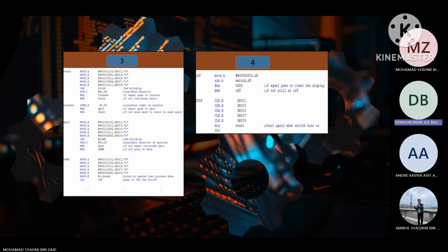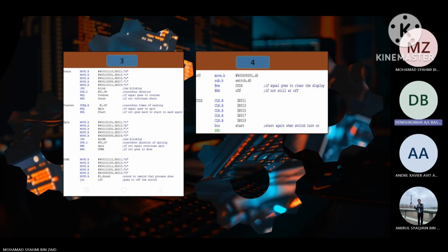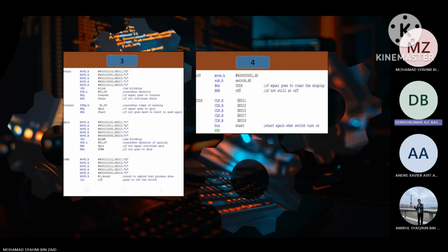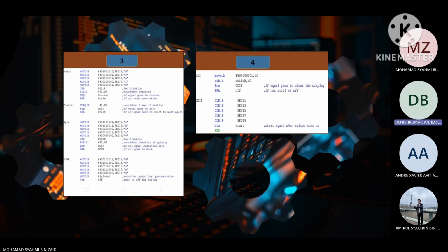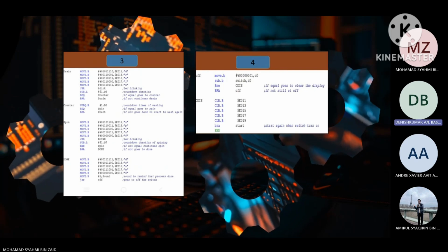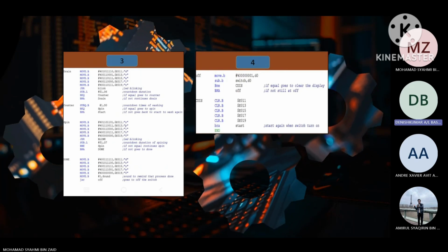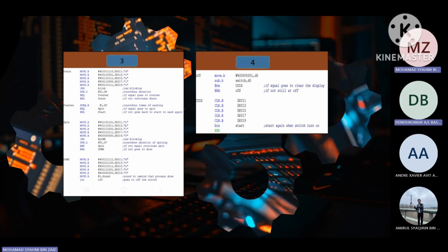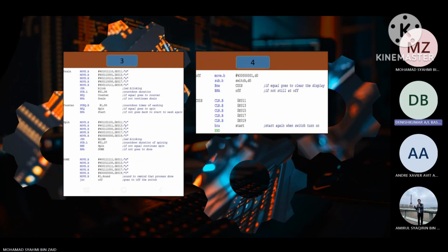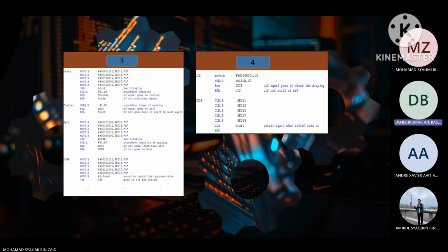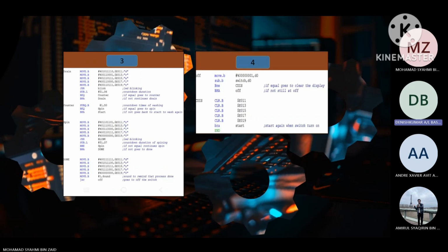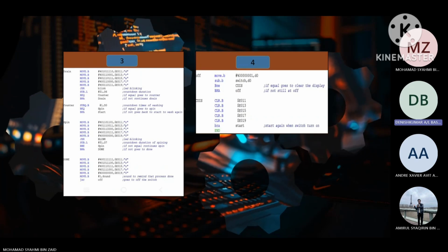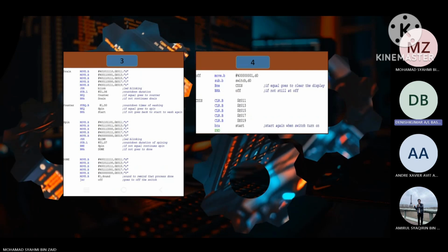The wash phase display shows WASH on the 7 segment display. The program uses GSR blink to blink the LED on and off. It decrements the wash duration D5 with the sub.L 1 to D5 and checks if the wash duration is complete. And the counter phase, the program subtracts 1 from the counter D0 and checks if the counter reaches 0. If the counter reaches 0, it will proceed to the spin phase.